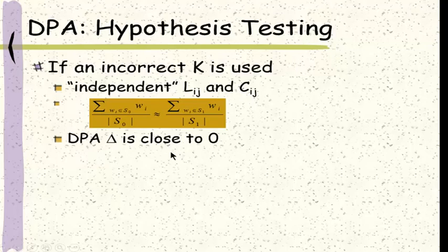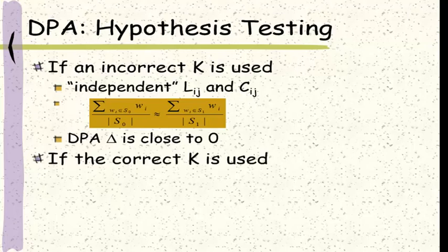However, when the correct key k is used, the computed output L sub i and the real output c sub i should be the same. Therefore, the power waveforms w sub i in the same subset should be similar, and the waveforms from different subsets should be different.